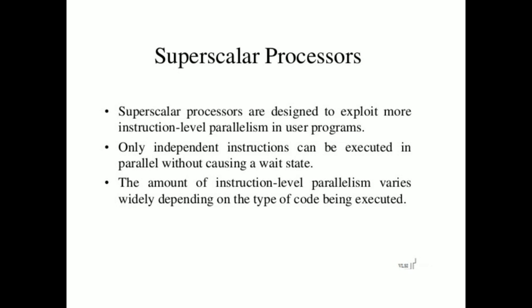In superscalar processor, there are multiple functional units, each of which is implemented as a pipeline. Each pipeline consists of multiple stages to handle multiple instructions at a time, which supports parallel execution of instructions.